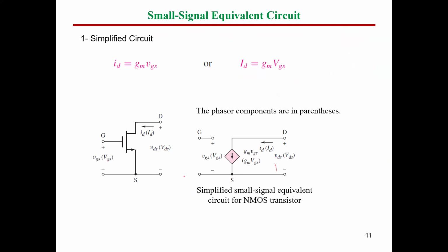So let's say now this is our MOSFET. The drain current is going to flow here, and this is the drain to source, and this is the gate to source. The gate to source can be represented by the input volt, and here you don't have a physical connection between the gate and the other parts of the element, so this would be an open circuit here.